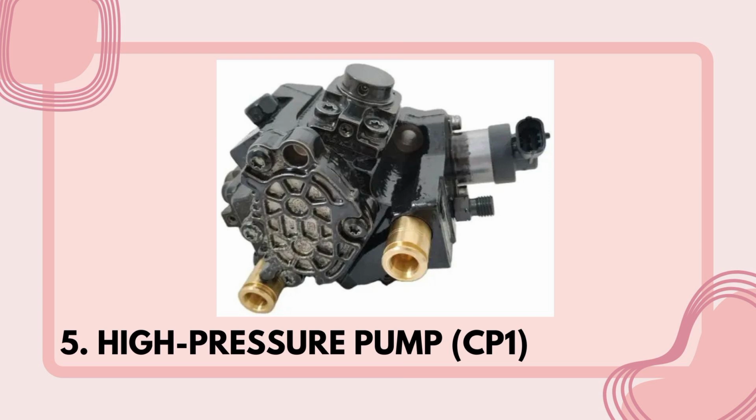Next is the high pressure pump. It is a pump that increases fuel pressure significantly. The function of the high pressure pump is to raise fuel pressure to the high level required for a modern fuel injection system, ensuring precise atomization inside the cylinder.